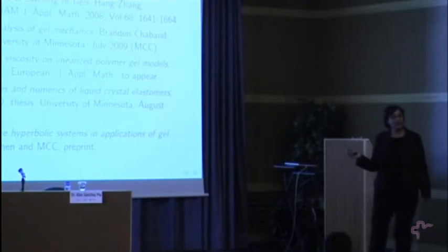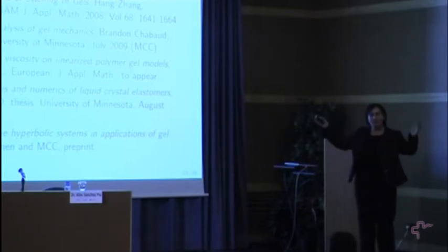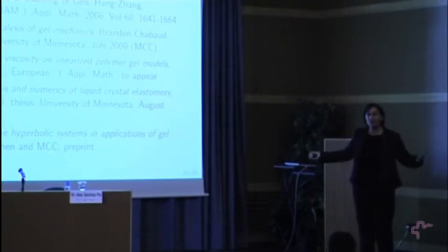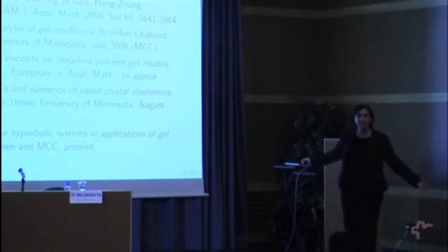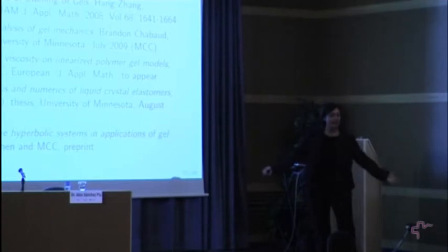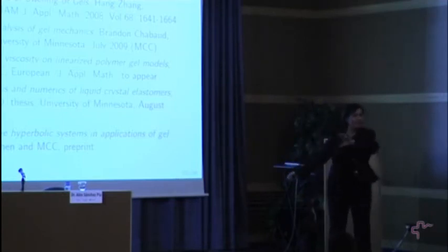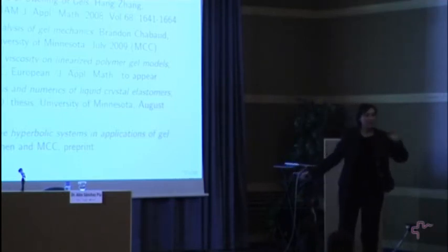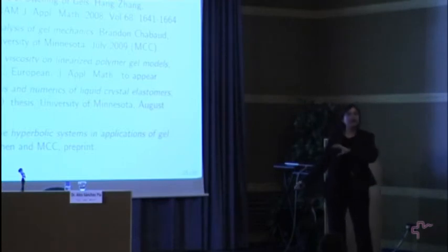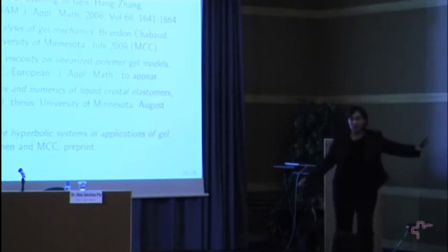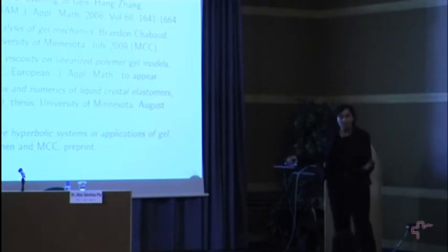And this was very interesting because when you have that whole system, all that page of equations I gave you before, of course, one thing you want to do immediately is a scaling. So you remove the dimensions, and then you get groups of parameters that have no dimensions, and then you can say, okay, if this group of parameters is much, much smaller than this other group, I am going to remove this one from the equations, and I get a system that is reasonable.